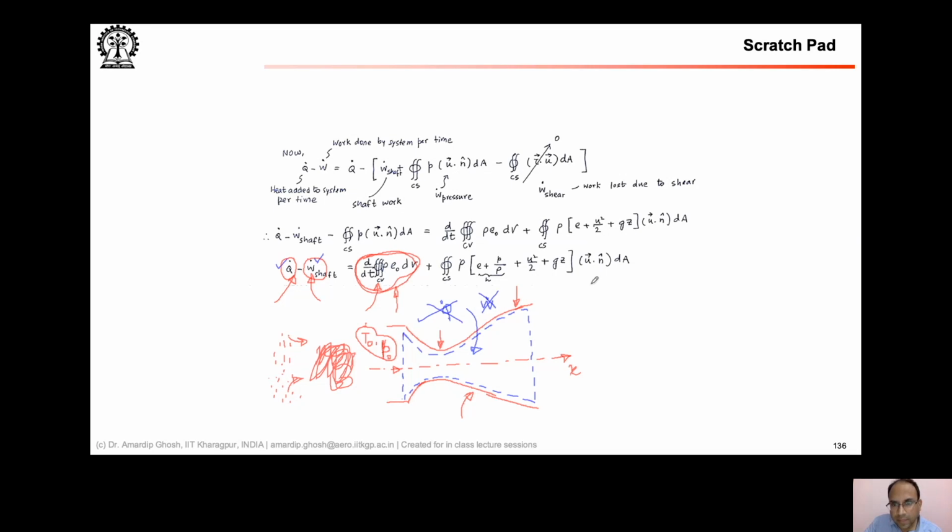So we are saying that, what is U dot N? On these surfaces, my N is directed like that, the normal outward direction. What about my velocity vector? It is also directed in the same direction. You can think of these flows as known as quasi 1D flow. Although your flow has some component in the y direction, it is approximated as if your flow is just a function of x. It's known as quasi 1D flow.